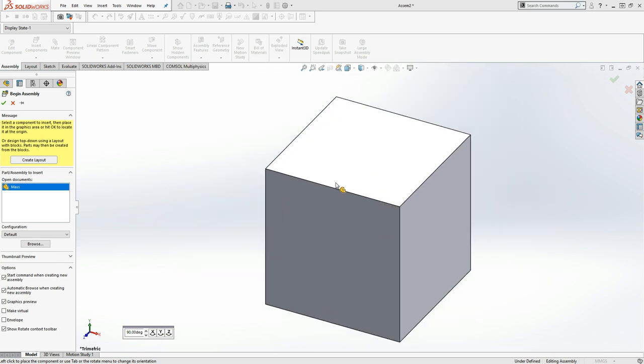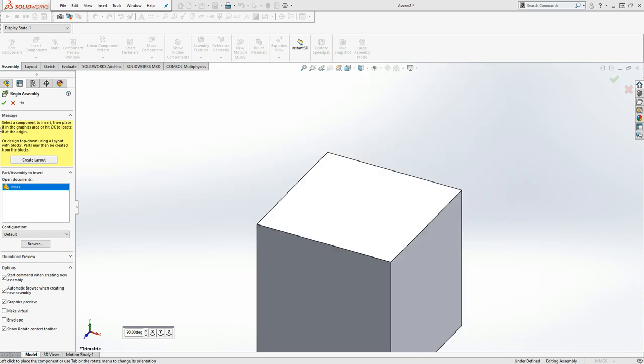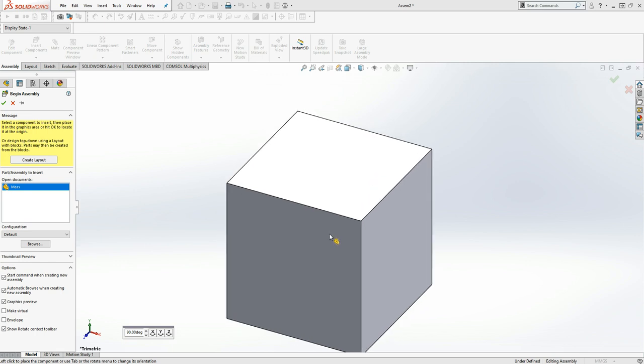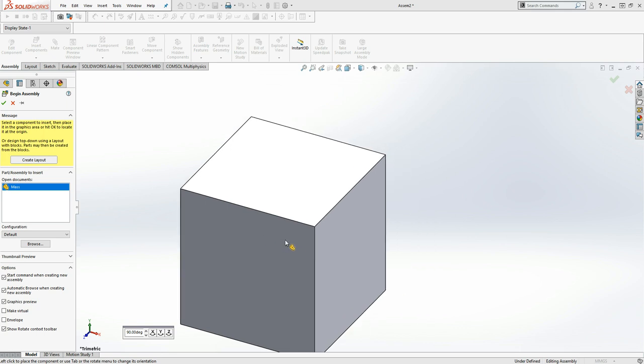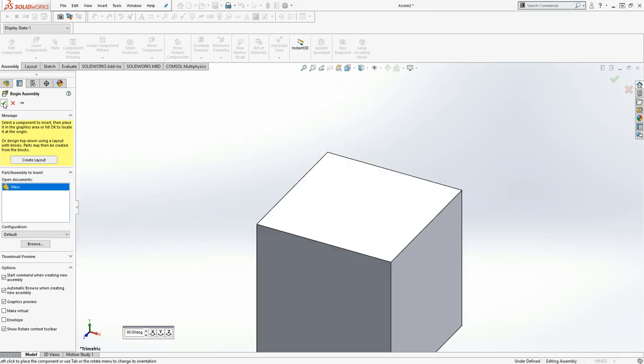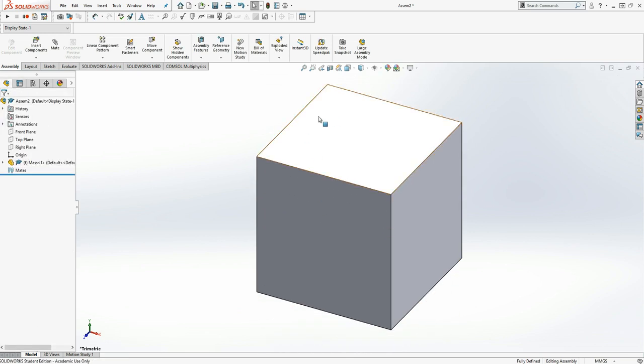I want the system to decide based on the original geometry that we did, because you remember we did an extrusion downwards, so that means that the origin to this piece will be in the middle at the top plate. So in other words, don't click anywhere, just click the green tick, and then you see there it moved, right?